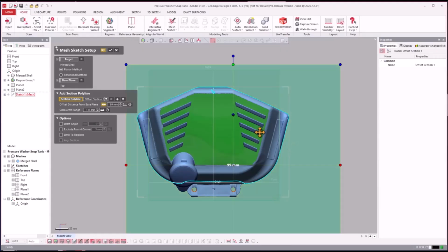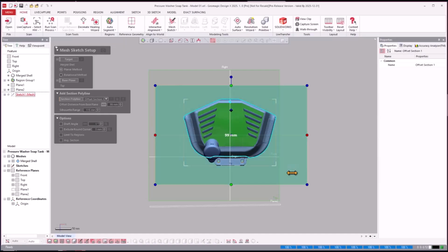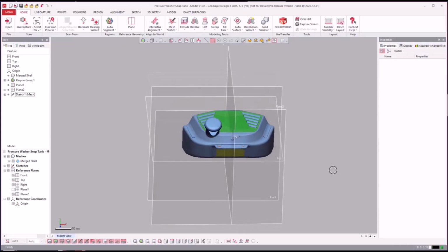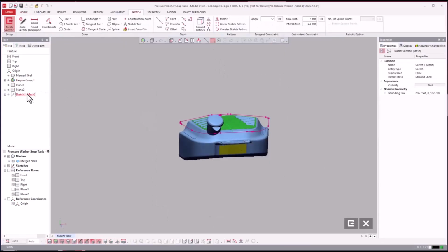And I noticed that before I went ahead and started drawing. But I wanted to point out that you can do this at any moment. You can move that mesh sketch boundary and then accept, and you can basically edit it on the fly. And then now I can come back over to mesh sketch. That's an important thing, that if you mess up, you can do that.